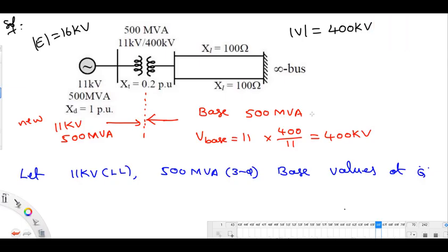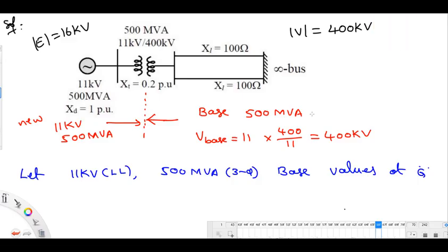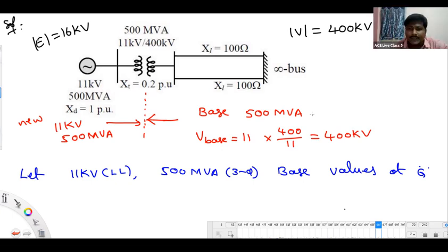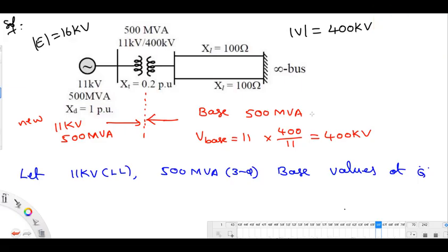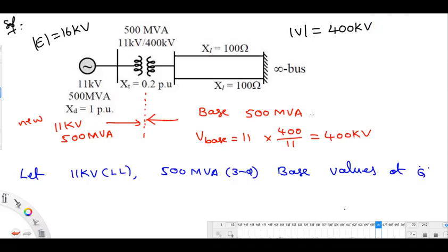I think so, sir. I went long back, 1 year ago. It is a shunt reactor to reduce the Ferranti effect. Correct. To reduce the Ferranti effect, they keep the shunt reactor, not to supply reactive power, strictly speaking. Okay. To control the Ferranti effect, they will keep the shunt reactor. Okay, sir. Only for that purpose they keep that reactor.